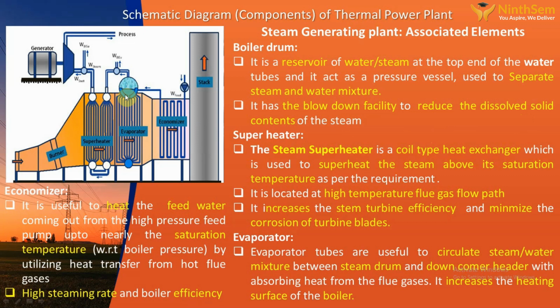You have to remove sediments from time to time by operating a drain valve or blow down valve. By opening this valve, we push the steam so that whatever sediments are there will be carried out and discharged to the outside. This operation is done routinely according to the water chemistry and water quality. So the boiler also has a blow down facility.